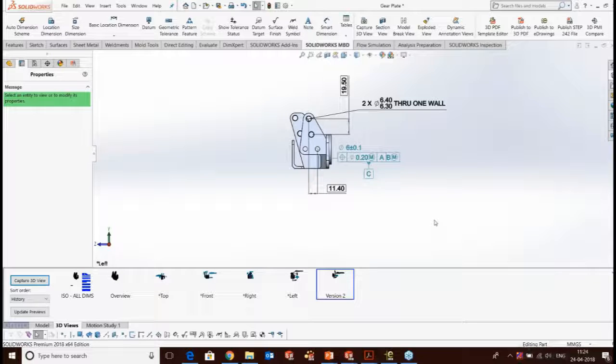Around 65% of the audience have voted yes for using eDrawings. It is a brilliant tool wherein you can share your designs or communicate your designs very easily and very effectively as well. In SolidWorks MBD, we have a brilliant option wherein we can export the product and manufacturing information, and also the complete detailing that we have added onto the model, in terms of 3D PDF as well as eDrawing.